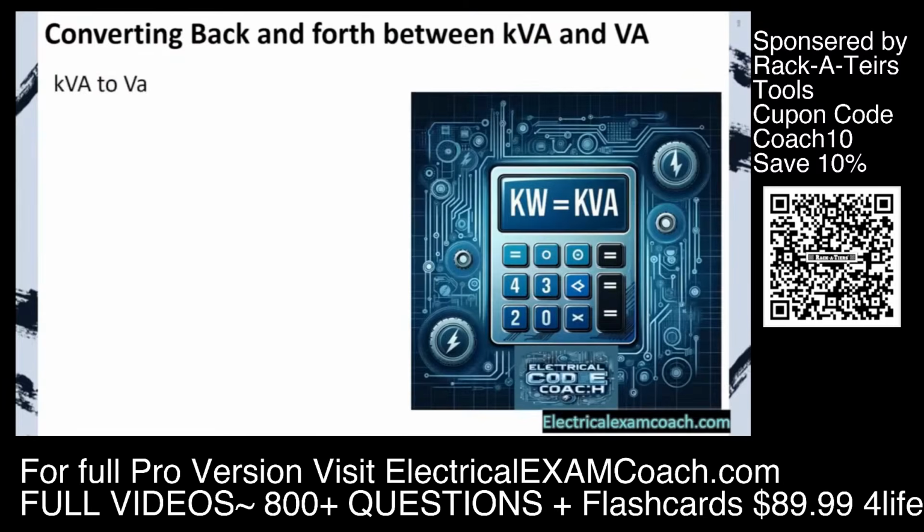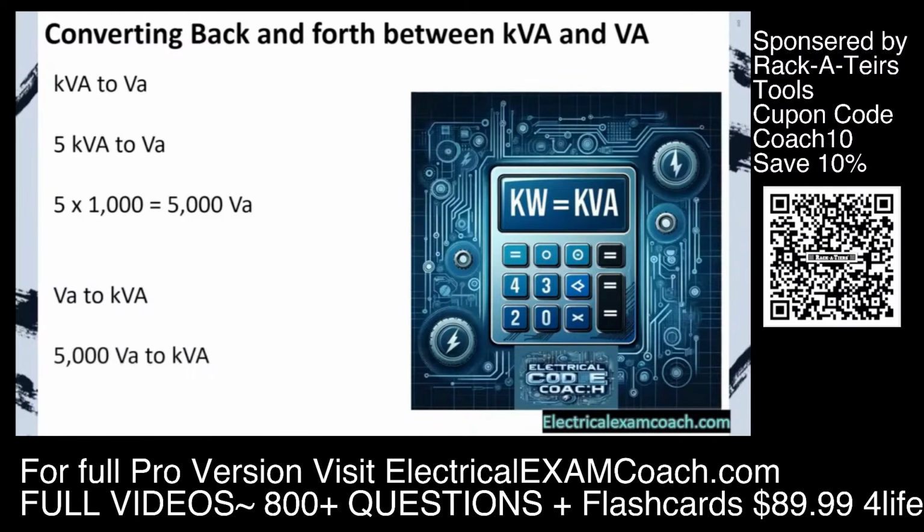Let's go from kVA to VA. So if we had 5 kVA and we wanted to go to VA, all we would have to do is multiply by 1,000, and that would equal 5,000 VAs. And the same if we wanted to go from VA to kVA, all we have to do is divide by 1,000 and it'll convert it over to kVA. You'll get very familiar with this and won't have to do any multiplying or dividing, but if you ever forget, that's all that you have to do.